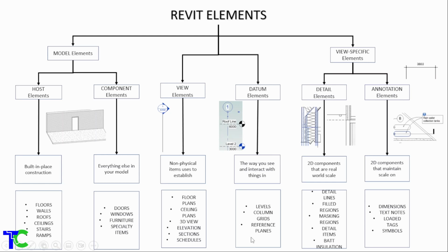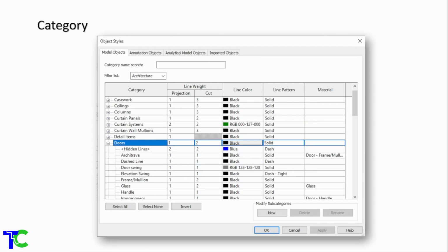It's important to understand that it's not possible to change categories as users. Elements automatically inherit the properties of the category. Every element in the Revit program will automatically use the correct category, and an element will never end up in the wrong category. That makes the category powerful. Categories impart many important special behaviors on their elements.